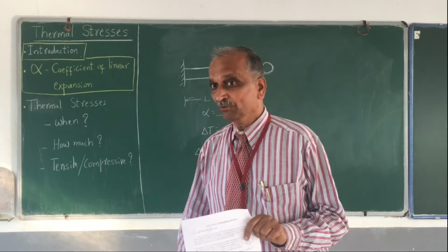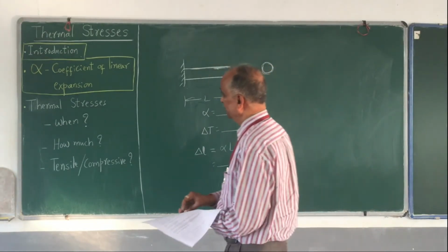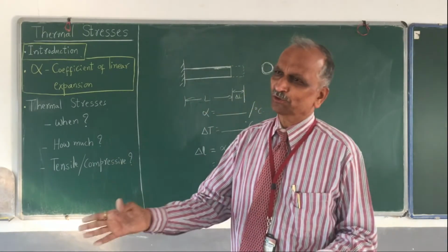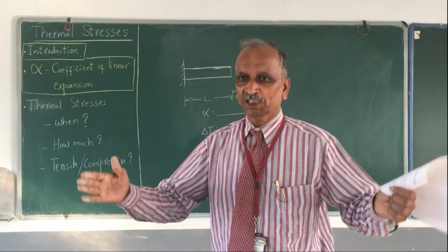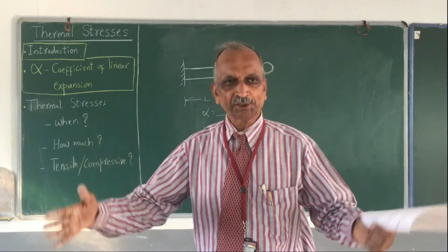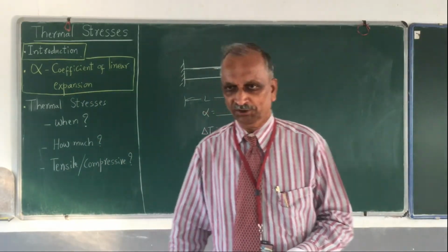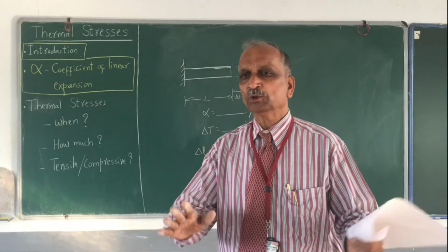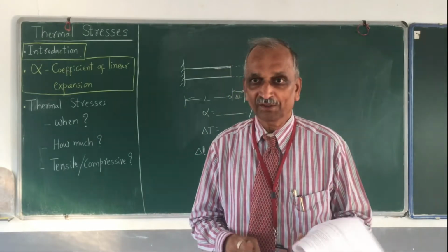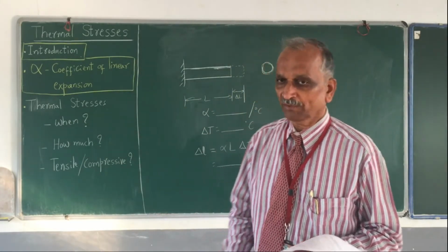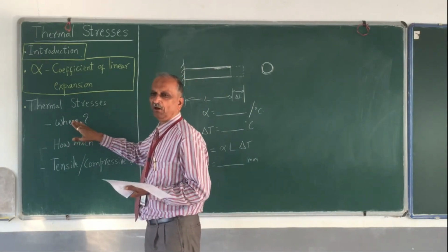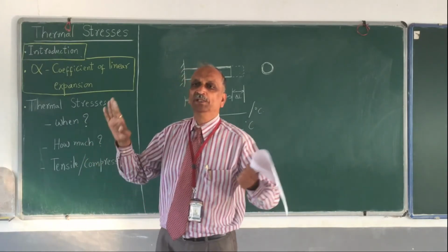So the question of stress will come into picture only if the free expansion, and this is true with free contraction also, is restricted. Expansion of a member because of the change in temperature, or contraction of a member because of the change in temperature, if you don't allow that to happen, then only the stress will come into picture. Thermal stresses are induced when free expansion or free contraction is prevented.